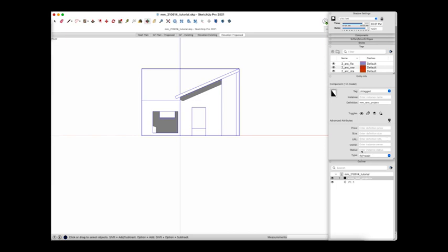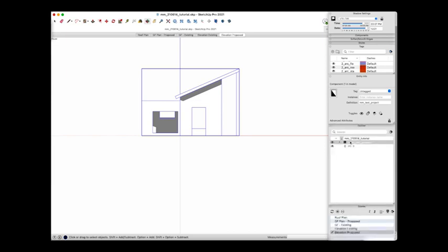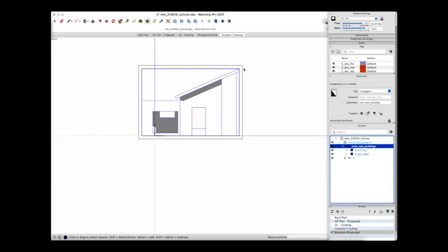And if I click inside the project, I've got a building. Now I'm inside project and I am into building. Inside building for this project, for this model, I only have a roof and walls, but the same theory applies if you had a more complex project. The important thing is that you somehow bind together the model in a component, and you assign the component the correct IFC definition. In this way, if you open the model in Revit, everything is going to be there as you need it.